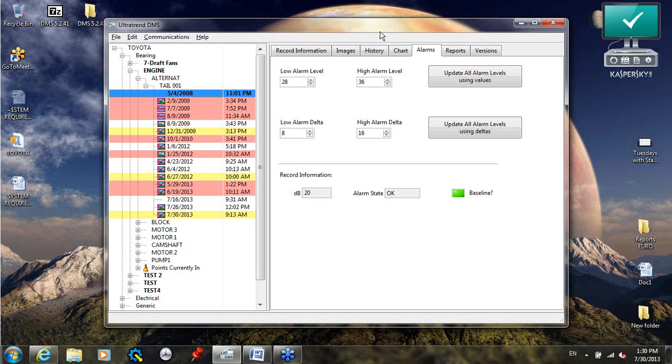Basically, the old style is, and I still deal with some people that are still doing it with the old ways. Periodically, they go by a time-based lubrication where every couple months they would have to throw in, say, 10 to 20 shots of grease into that bearing, because that's what the manual is telling them to do. With ultrasound, you guys can use the ultraprobes to detect when the bearing is full.